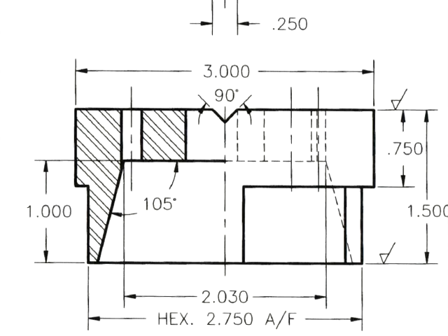In the case of this bench block project, well, we have a half section that's presented in the bottom view. It's called a half section because only half of the part has been sectioned. This gives us the best of both worlds because we can see the inside as well as the outside, all in the same view. And in this case, it makes that tapered cavity a lot more visible.